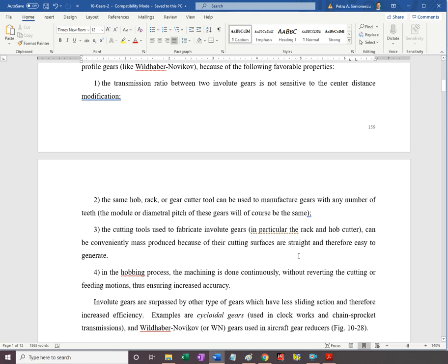We looked at the manufacturing processes, and there was one, form cutting, that's excluded there. You need a tool for same tooth proportions, same circular pitch gears. But if the number of teeth differ by one or two teeth at most, then you need a different tool.